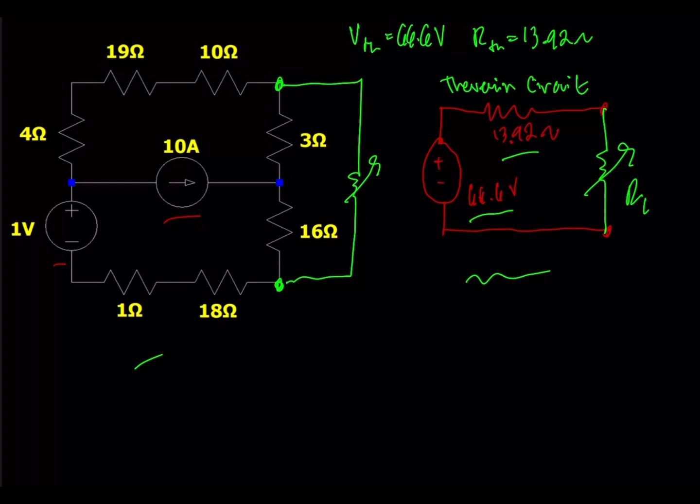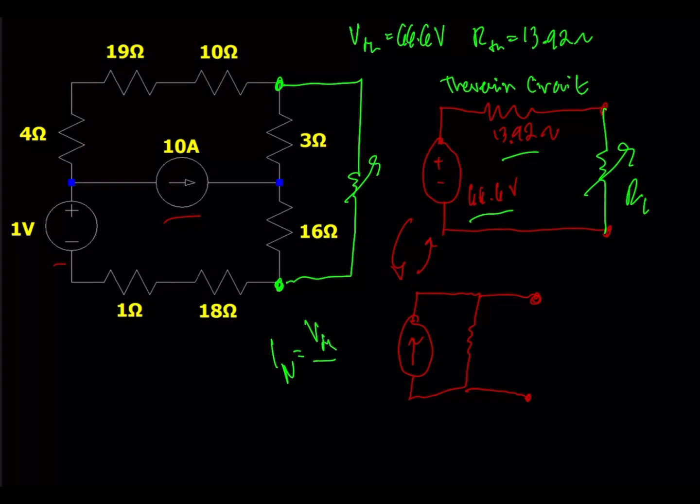And Norton's theorem states that simplification gives us an independent current source in parallel with a single resistor, as opposed to Thevenin's. Now here we've covered source transformation, so we can swap between these two configurations really quickly using those equivalencies we found. So this Norton current is actually just the Thevenin voltage divided by our Thevenin resistance, and that was found from source transformation.